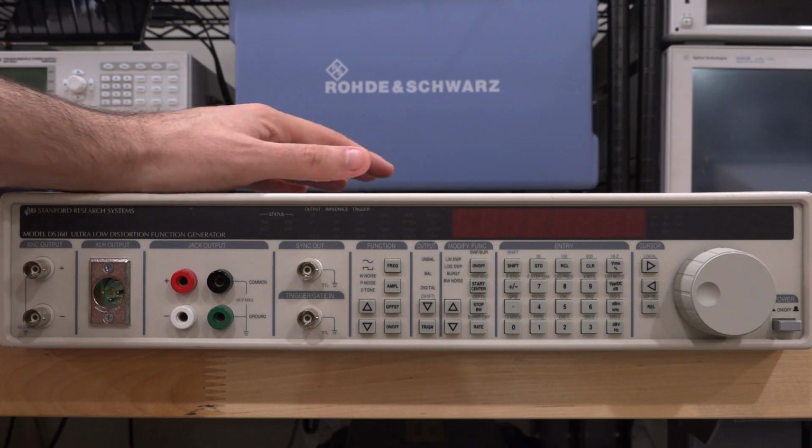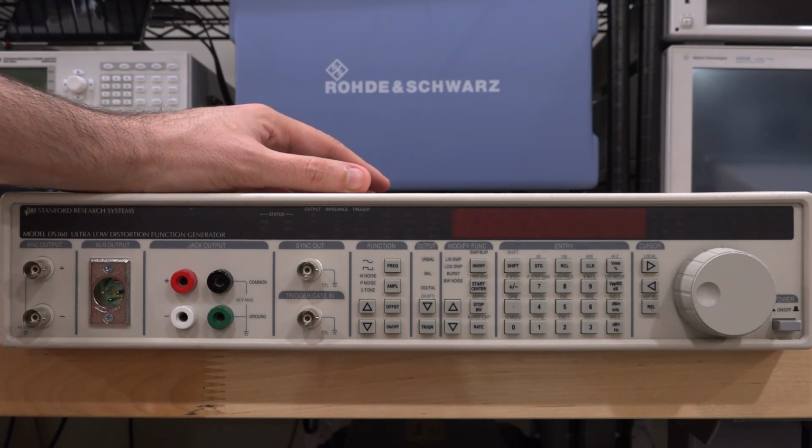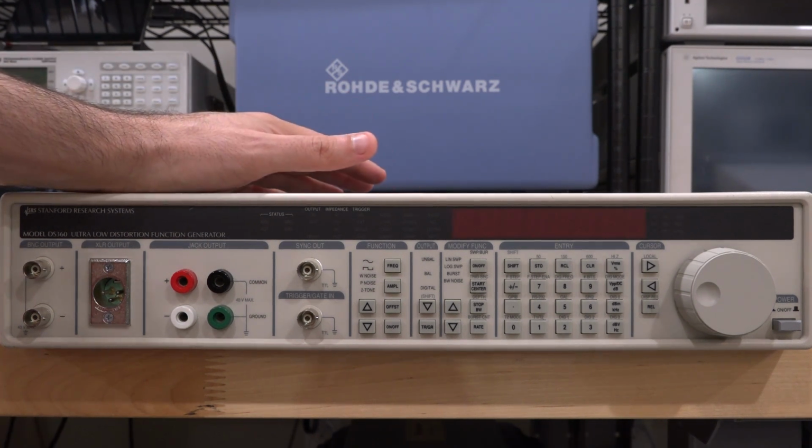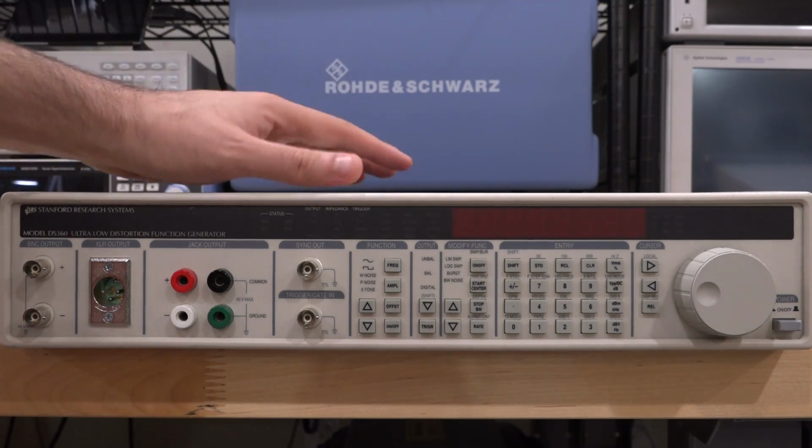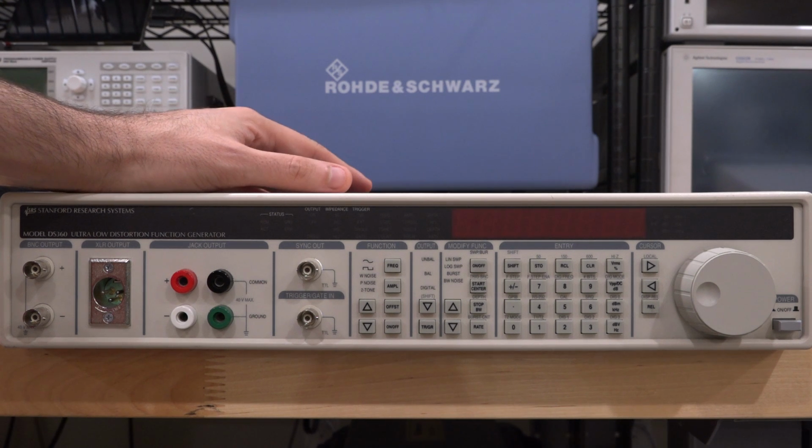And that's because this thing is such a clean source that when you use it, you're going to make sure that you're measuring your device under test and not your source generator. If this thing has a poor THD, then you just basically measure this thing. You would never know what the performance of your data converter is. And ever since, I've really wanted one of these in the lab, so now we have a chance to work on this.